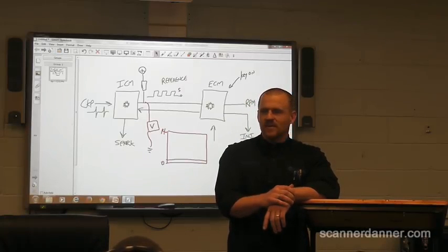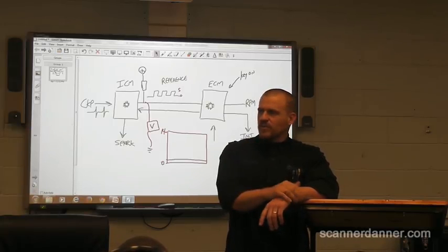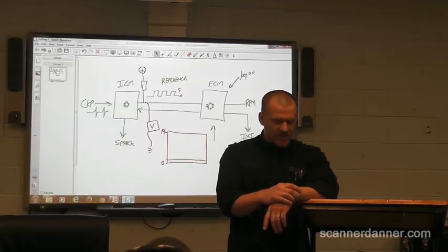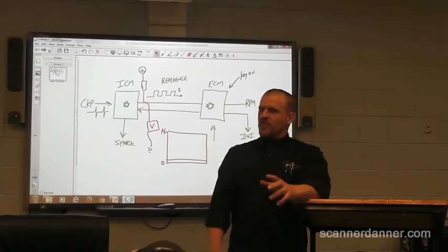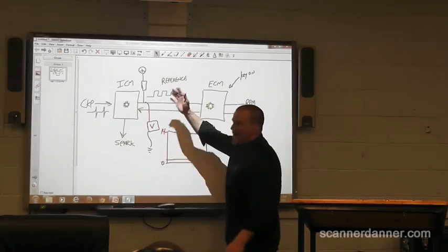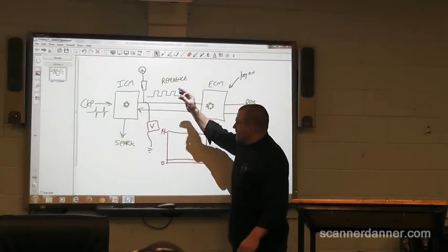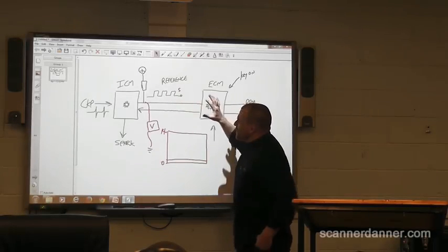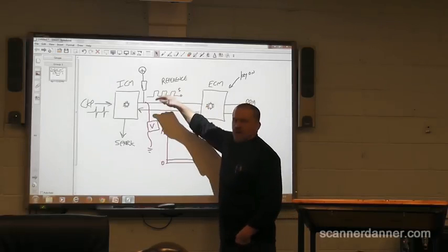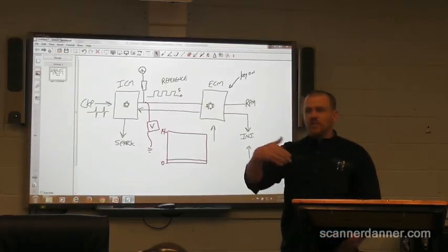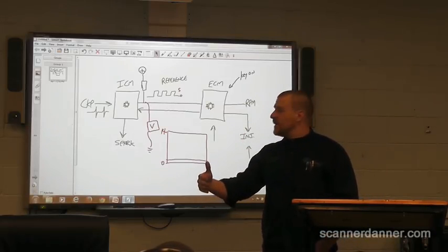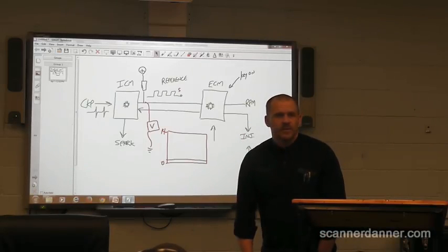So did the test. The old troubleshooter in the Snap-on scanner, they called it a scratch test. And I just remember that test vividly. One of the things you wouldn't want to see, a bad scratch test where we're touching this on and off and looking for a reaction, a bad test would be when you touch on and off of this, nothing happens, no injection pulse. Where does that move us away from when we don't have a reaction?